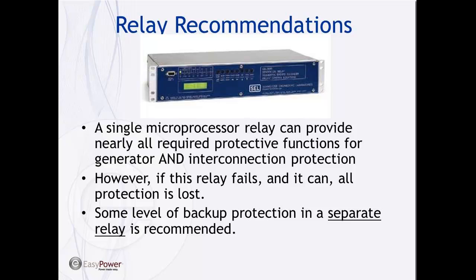However, if this relay should happen to fail, and they definitely can, you go from having wonderful protection to having absolutely no protection. So you're going to want some type of backup in a separate relay. Some people will just duplicate these two relays, have identical relays with identical settings, and that's fine.